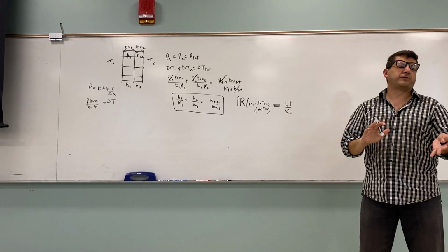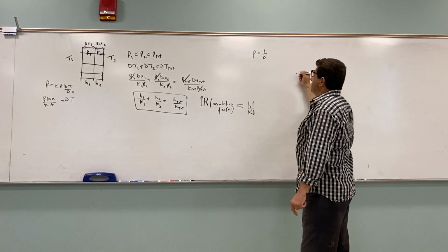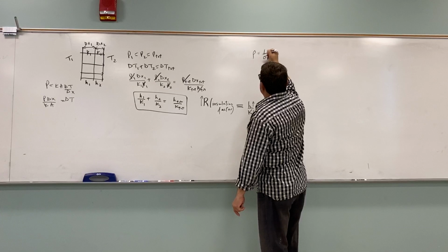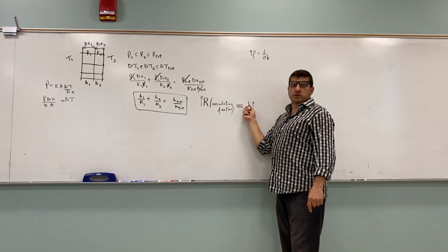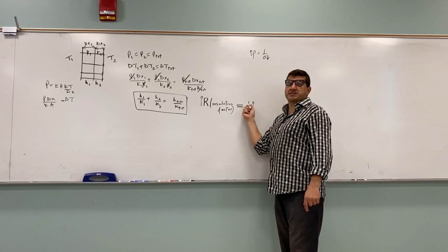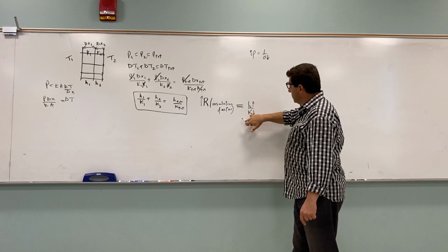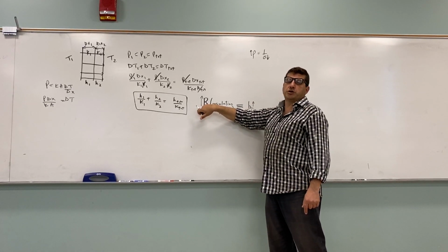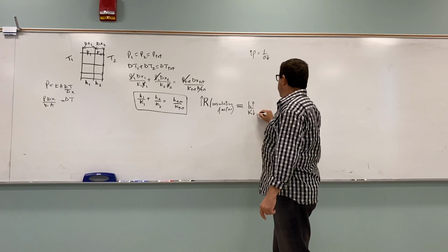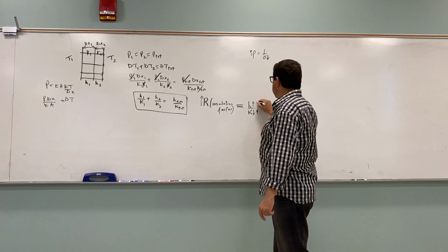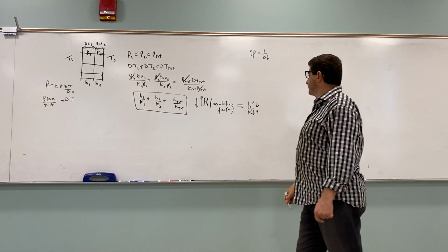So it's kind of like what we do in electricity when we have resistivity, which is 1 over conductivity of a material. So if it's electrically a bad conductor, then it's a good resistor. Except now we're applying that to the total resistivity. So it also depends on the thickness. So not only the material, if it's a poor thermal conductor and also thick, then it's going to have a good thermal resistivity. So obviously the opposite will be true. If it's a good thermal conductor and very thin, the insulation will be low, right?